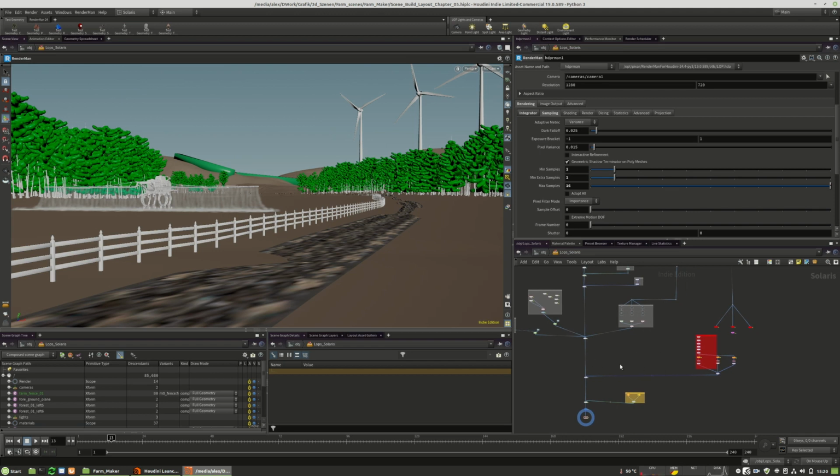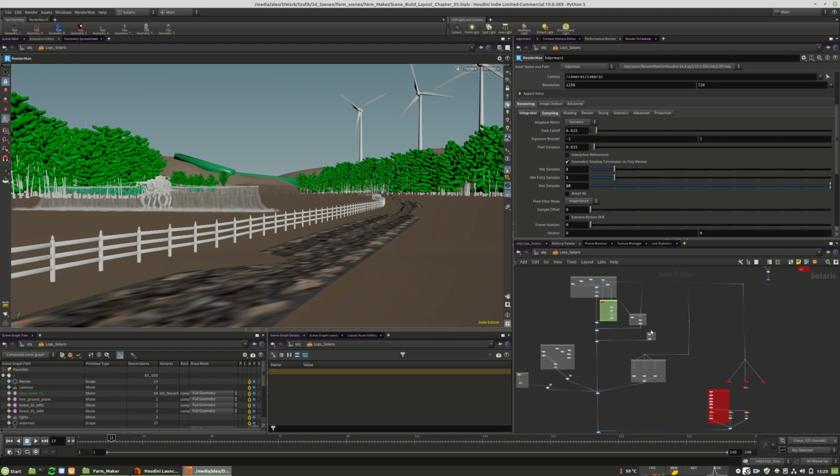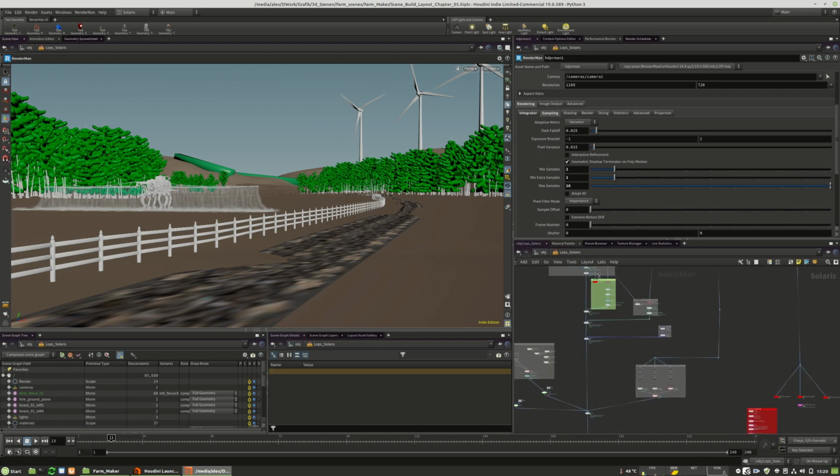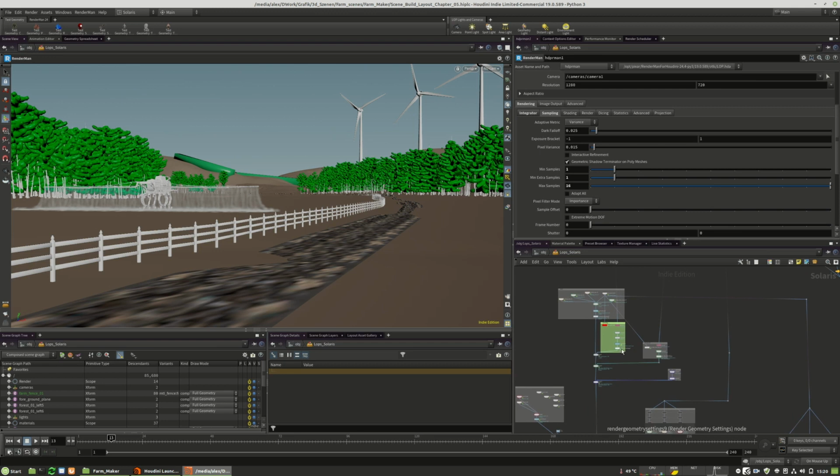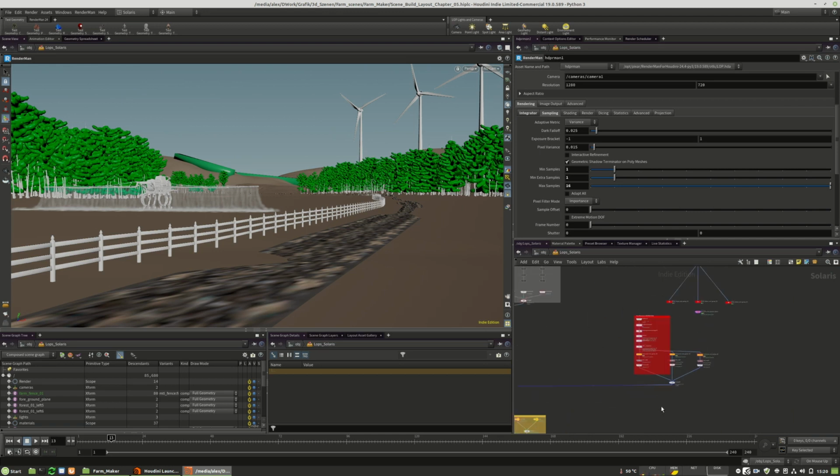The first thing in order to save render time is to bring all the data that we have here to an SSD disk. When I started with the project, all of my files were stored on an HDD, and now I have moved all the assets to a scratch drive, an Evo 970. This M.2 disk has a very fast reading speed, over 3000 megabytes per second, and this is a really good way to optimize the time to first pixel.